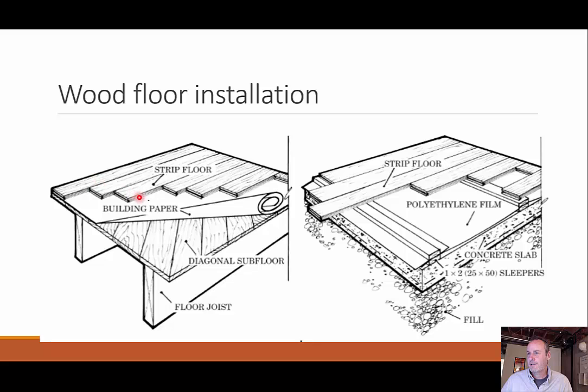And then I can start applying my hardwood, and we could do our hardwood on top of the subfloor, or as an alternative, if I do have a concrete slab, I have to build up from that concrete slab, typically with what are called sleepers. So putting these 2x4s on end to give me something to nail to and support. I cannot put the hardwood directly on the concrete without it being an engineered wood or a floating floor system or something like that.